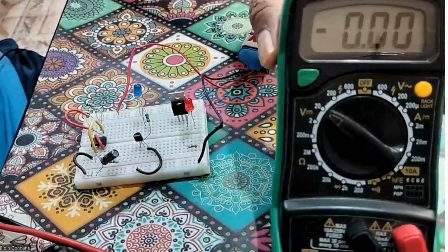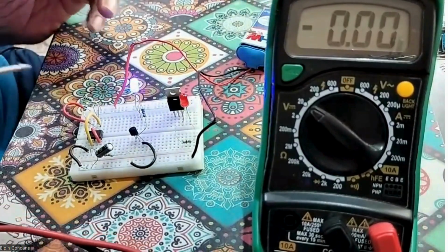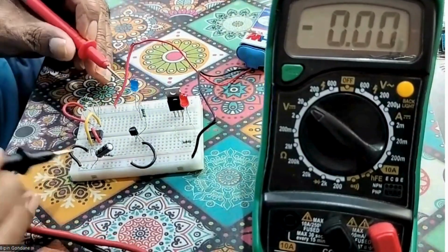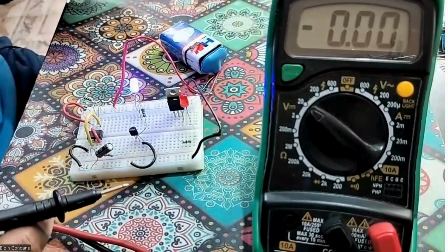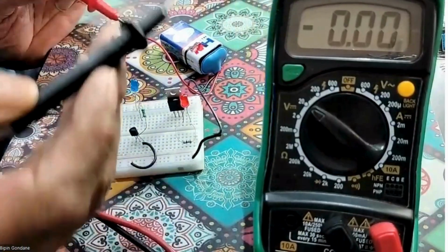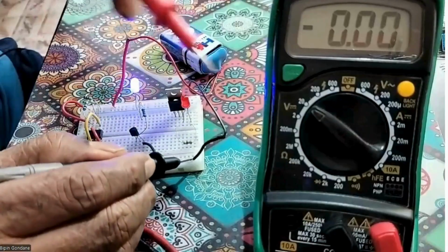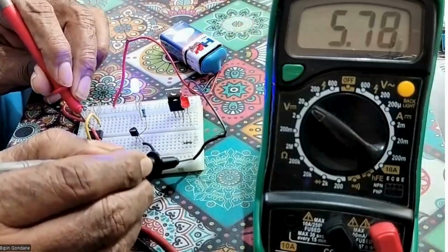So how to test this circuit? I told you how to test the IC. Please remember, wherever the supply pin is going, you have to check whether the supply is all right or not. I have given a supply of approximately 8 to 9 volts from here. I will check whether my supply is okay. This black probe I'm putting on ground, with the meter on the voltage range, and the supply is going to pin number 8 of the IC.